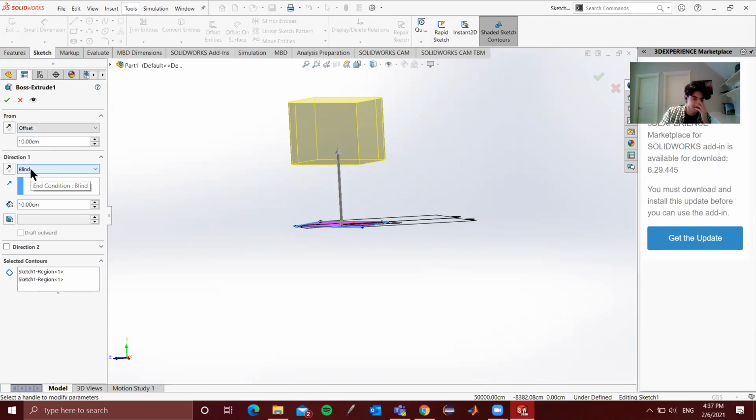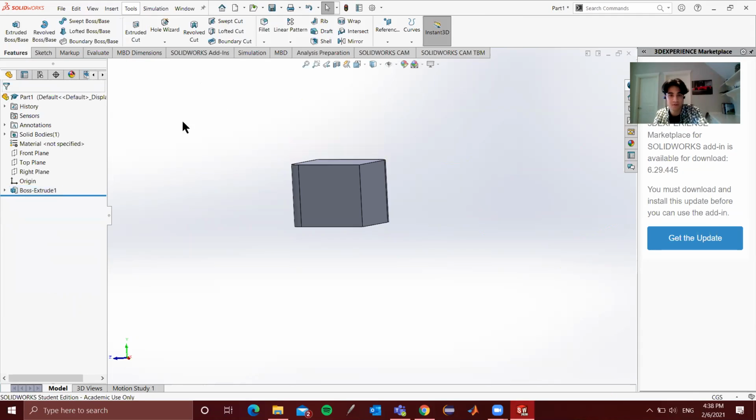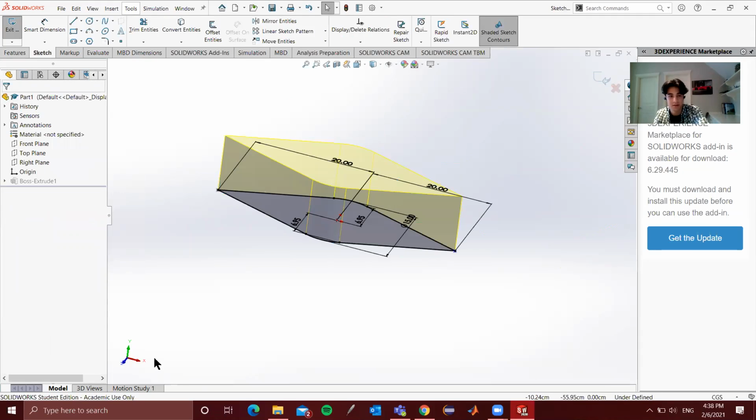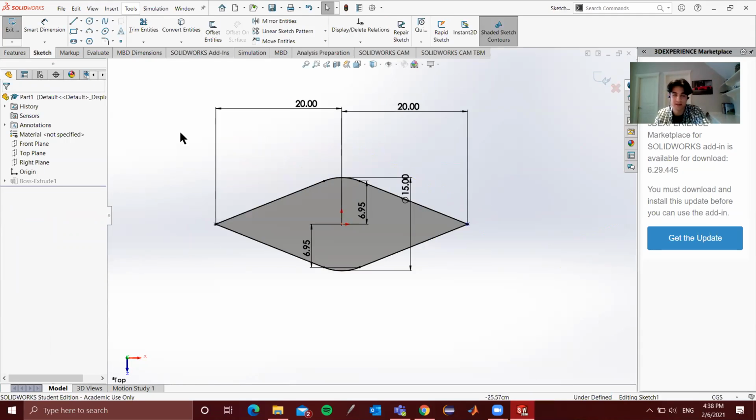As for the types of extrusions, you can do it up to a surface. So similar to the extend tool that I showed, if you have another surface that's on the same axis, so it's going to intersect if you extrude this by a certain amount, the extrusion will actually go up to that surface. So say if I quickly go back and within our sketch, I'm just going to create an offset sketch.